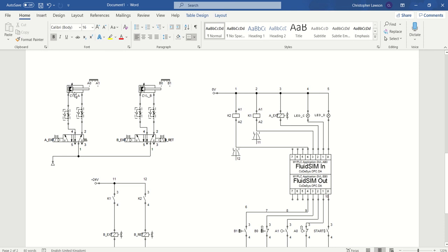So when I need to move this forward, I need to latch this on to make it go forward, and then break the latch to make it come back. With this type of valve, I only need to give it a pulse at the output going forward, and it'll move forward for me. Okay, there's nothing springing it back.